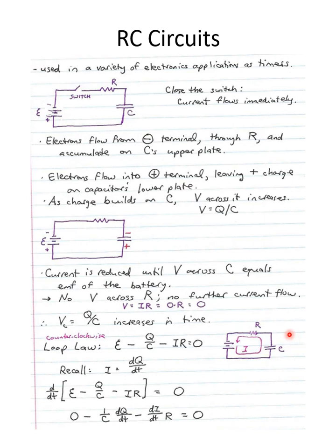And then we're going to subtract the voltage drop across the resistor by Ohm's law, that's current times R. And when we make it all the way around to the battery on the other side, the total of the voltage should be zero. That's what the loop law is. The battery steps it up, and then that same voltage gets dropped down, and it comes out to be zero.